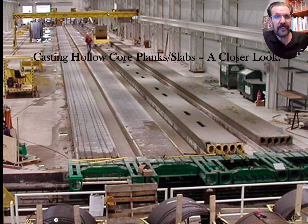They literally have this track right here that's running around here, and they got this device that rolls along the track that they pour concrete into a hopper and fills up this machine that vibrates and shapes the concrete into the hollow cores, including the hollow tubes that you see shaping up here. And they just make one really long hollow core slab that's running the whole length of the building on these pedestals.